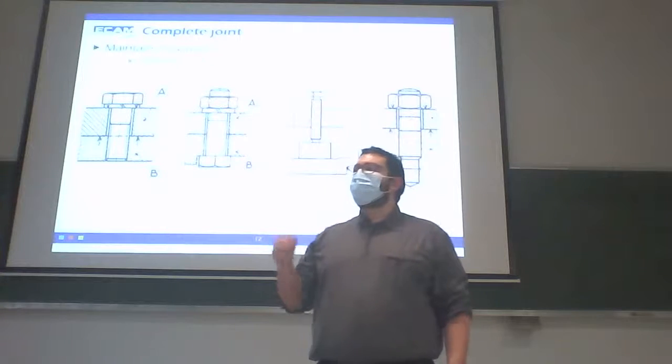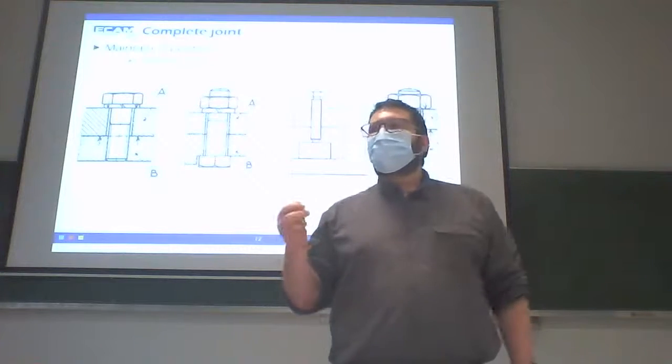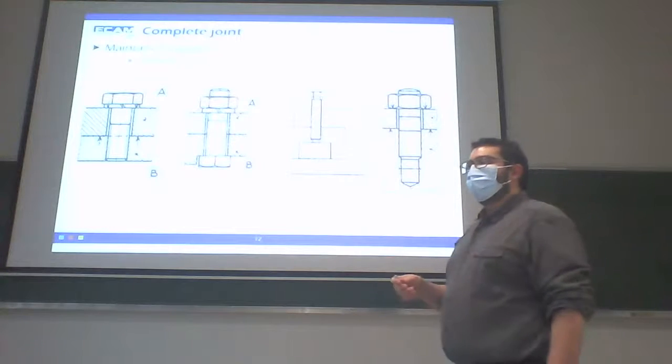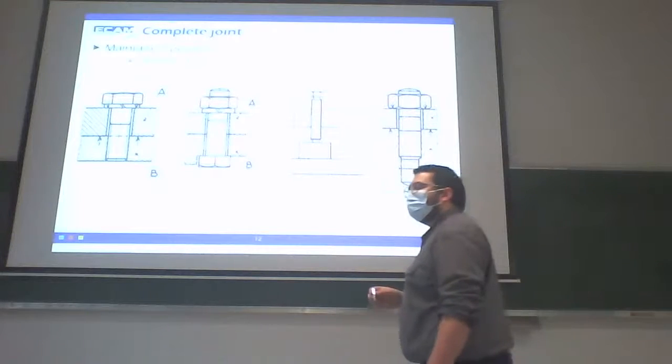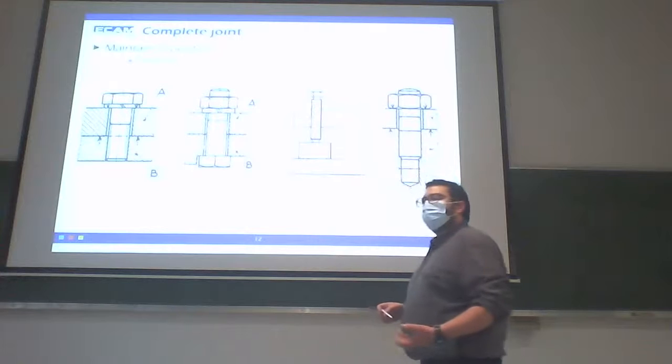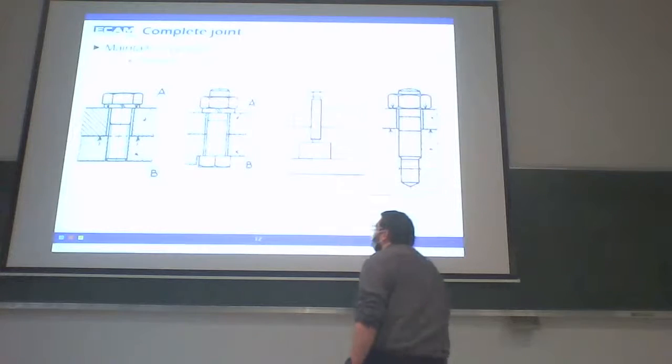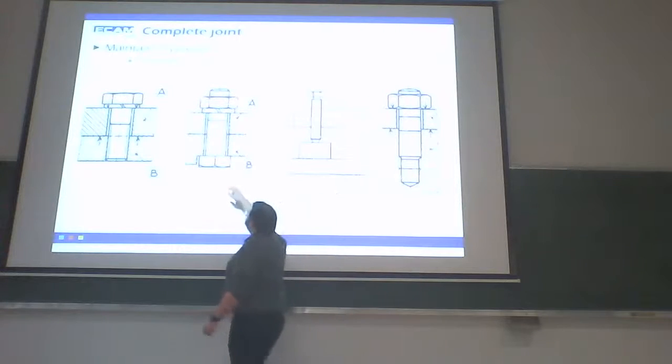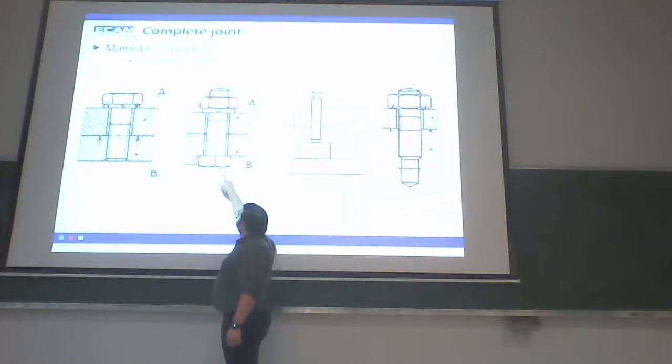We prefer to use a pin because the size of a pin is more precise. The screws are just here to maintain position. It's the same here. We'll use a nut and a screw.